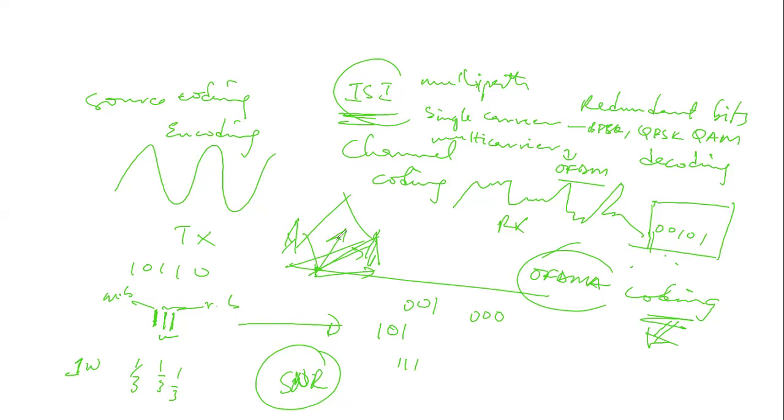So we now have multiple components of that same signal. At some point, multiple components of a particular signal having the same frequency now interfere again. They could cancel out. They could even amplify, combine. So that alone distorts the exact signal coming in, so it causes intersymbol interference. At the end of the day, when we're supposed to be receiving 10110, we are receiving 00101.